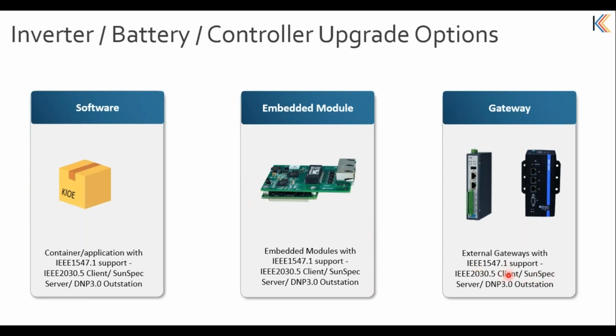And it can be an external gateway option as well. For external gateway options, there are different hardwares available depending upon the applications and the number of inverters. If there are multiple inverters on the site, you can connect multiple inverters to the gateway, and the single gateway can comply to any of the standard protocols. But as I mentioned earlier, if it is an external gateway, the certification will be for the packaged option with the gateway plus the devices, not for the individual device. It will not have the full compliance of this standard.